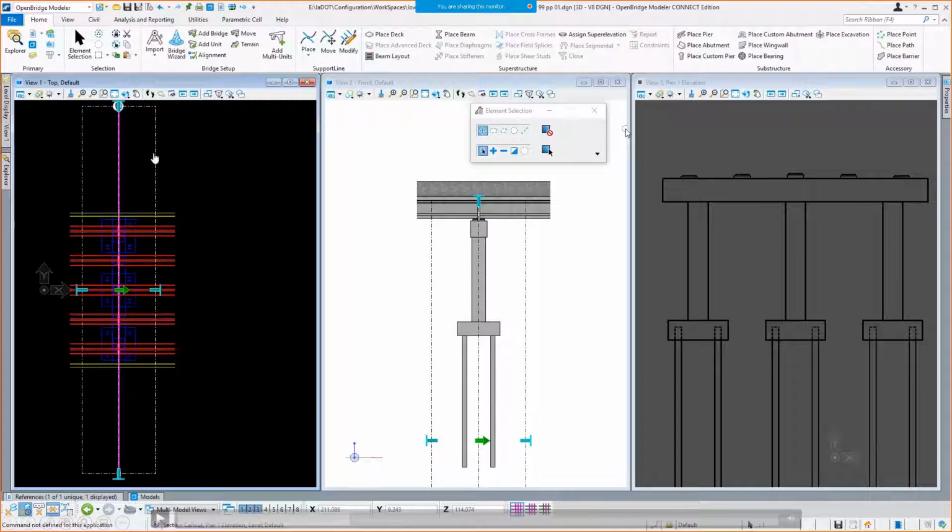So this is your forward clipping plane. So anything inside this rectangle right here, between this purple line and this white line, this is the forward plane. This is your cut line. This is your forward area. Anything from this line back to this one, that's your back area. Okay. And then there's a fourth term, we'll see it here in a moment, called outside. So if it's not at the cut line, if it's not forward, it's not back, then it's outside of that area.